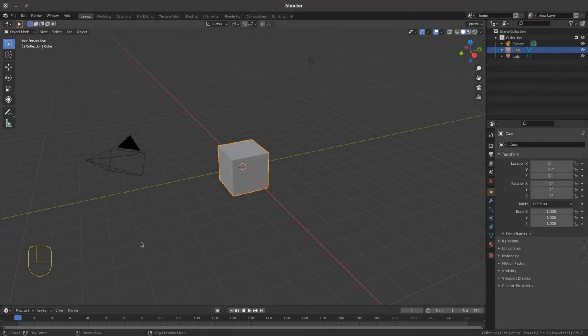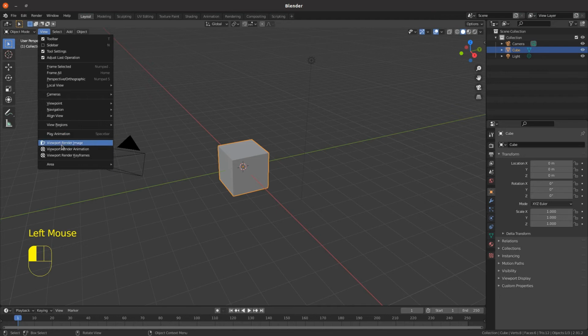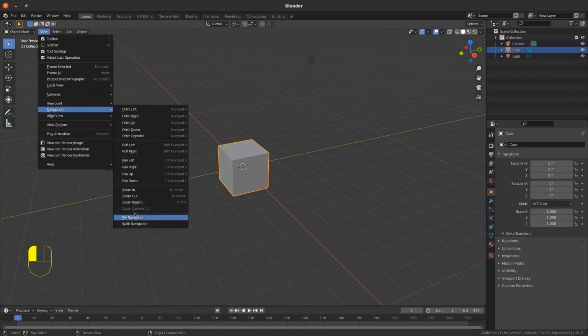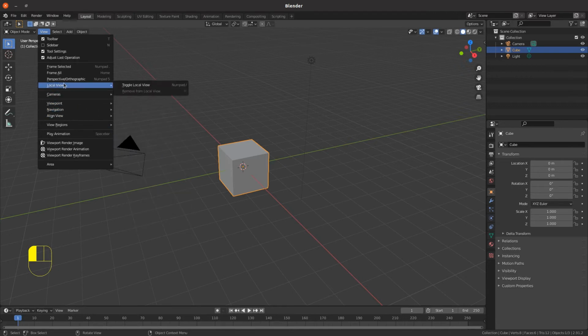I haven't covered all of the view navigation options because there are quite a lot of them. But as you work through these tutorials and we get into the more practical elements, then we'll be bringing some of the others up. You've also got the option of going up to the 3D viewport's menu and just clicking on View, and that lists all of the available options for what you can view. So as we talked about, the navigation, orbits, pans, zooms, and everything is there. And fortunately they give you the shortcut keys that you need to use if you want to learn the process of using Blender efficiently using the shortcut keys.